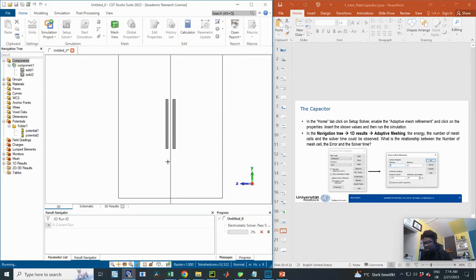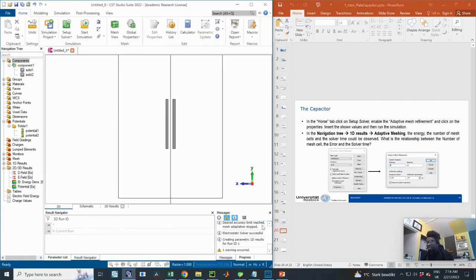So this is going to take, okay, maybe not very long because it's already in pass 5. So each pass is a level of refinement. So we have pass 1, which is your default, your initial mesh resolution. Then you have pass 2, it refines it. Pass 3, pass 4, pass 5. Then if it satisfies the condition you gave, which was the stopping criterion, before 8 passes, then it stops automatically. Otherwise, it gets to 8 passes, and whatsoever the accuracy is there, it stops.